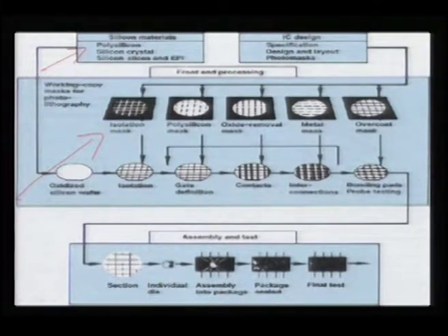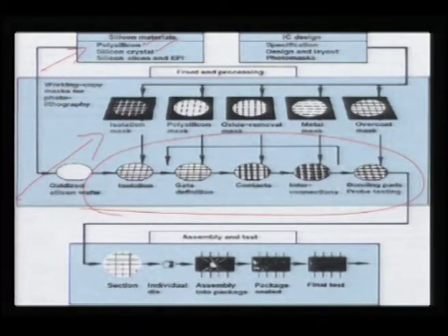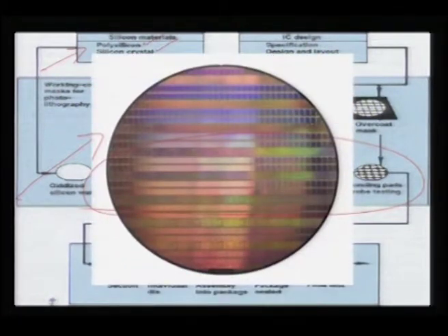Therefore, we can talk about silicon crystal, which is oriented single crystalline, and polycrystalline silicon, and this is the way most of the devices are made with base material such as a silicon wafer, and typically the sizes that we can achieve out of these silicon wafers are 6-inch, 12-inch wafers.